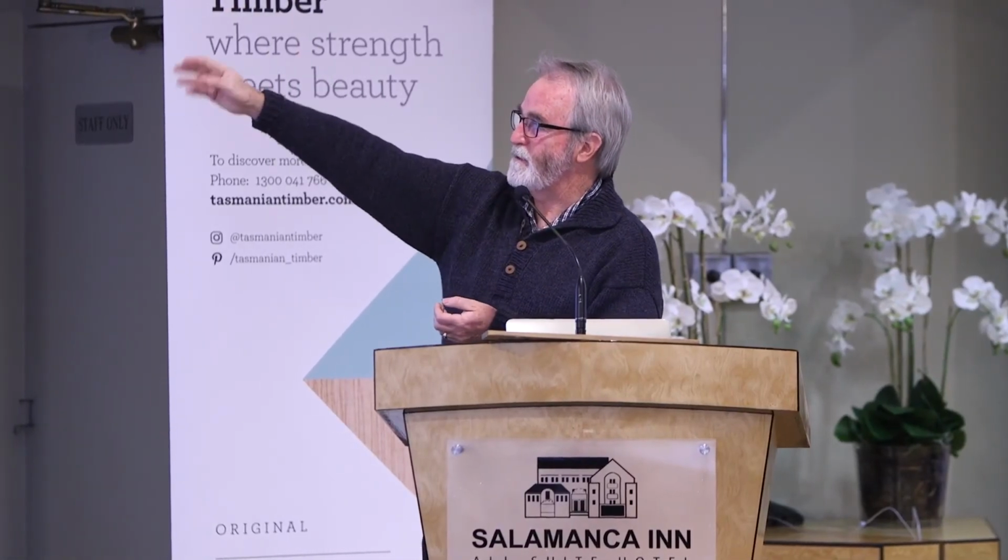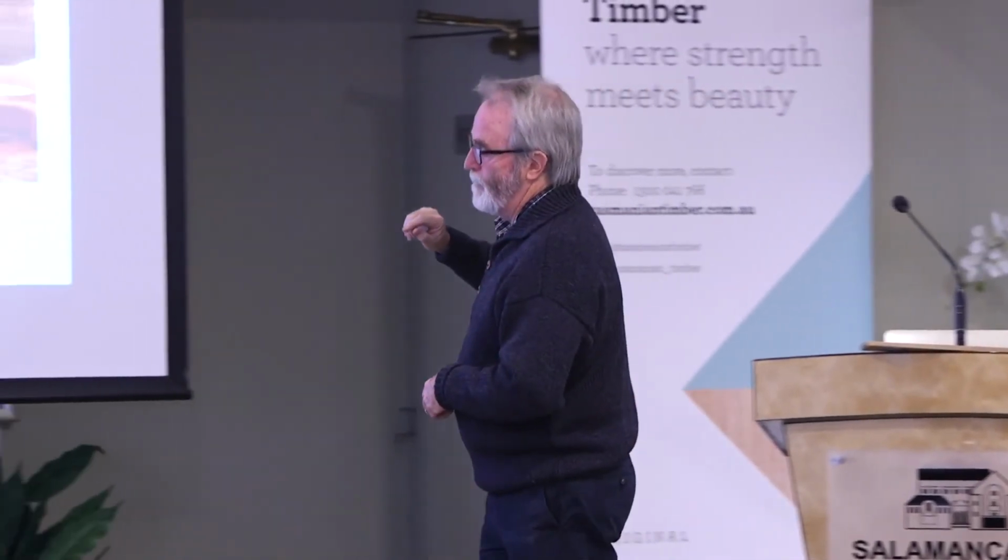If we look at these four, for interior applications, our two big ones are hardness and fire resistance. Hardness is primarily going to kick in if we put something on a floor or a wear surface, in which case the hardness of the material becomes important. Because if you put a really soft material on and it's in an arcade and there's 2,500 people walking over it every day, they're going to total it really quickly. So that's a key factor.